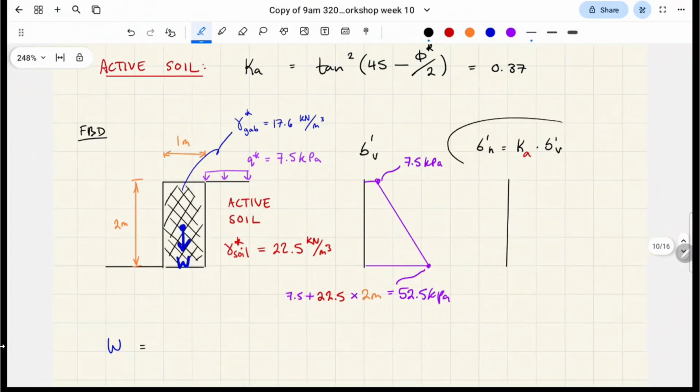Here I'm going to be graphing right next to it the horizontal effective stress. Here I've included just this part of the formula, but it keeps going and has a component for cohesion. Because we're dealing with sand, I've excluded that portion because c is 0, so I'm not going to write that in.